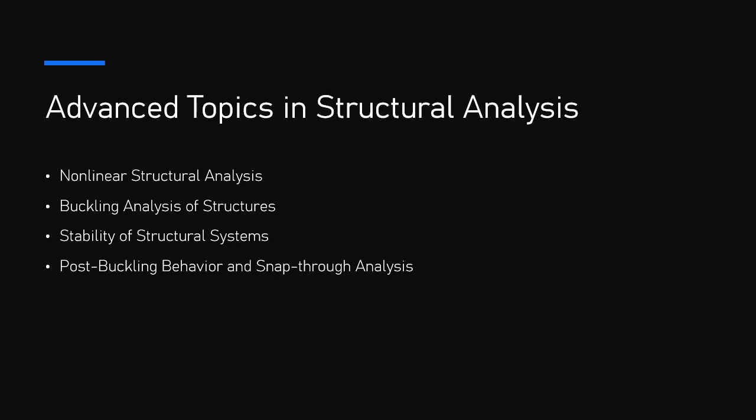3. Pushover analysis. In the case of nonlinear buckling, post-elastic behavior, a pushover analysis is often used. This involves incrementally applying lateral loads to the structure until it reaches the point of failure or instability. 4. Modal analysis. Modal analysis helps to predict the buckling modes and corresponding critical loads for structures subjected to various boundary conditions. The first few modes are usually associated with the lowest critical buckling loads.